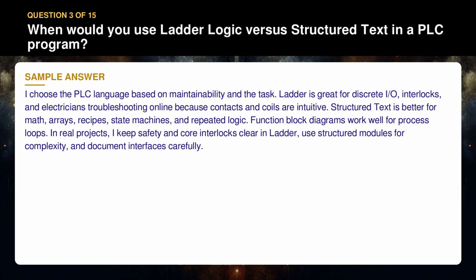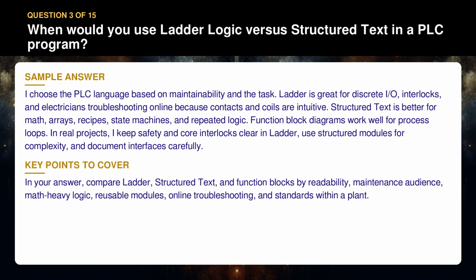In real projects, I keep safety and core interlocks clear in ladder, use structured modules for complexity, and document interfaces carefully. In your answer, compare ladder, structured text, and function blocks by readability, maintenance audience, math-heavy logic, reusable modules, online troubleshooting, and standards within a plant.